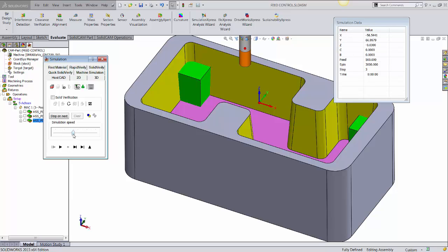okay, let's go a bit slowly. It's still running at 1000 in spite of the corners, because the feed reduction will happen only from that point below. Okay, now I can see that as it comes close to that particular zone, it will automatically drop down the feed rate to 750. It won't keep it at 1000.